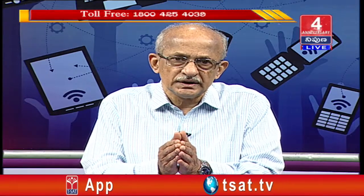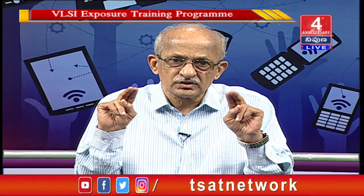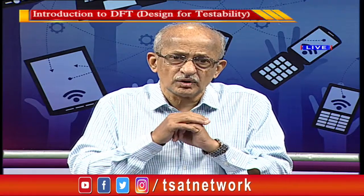Therefore some hardware and some logic will have to be introduced so that when the chip is going to be tested, it will facilitate testing in an easy way and improve what is known as controllability and observability of the internal nodes. This is very important in DFT, and the challenge lies therein.